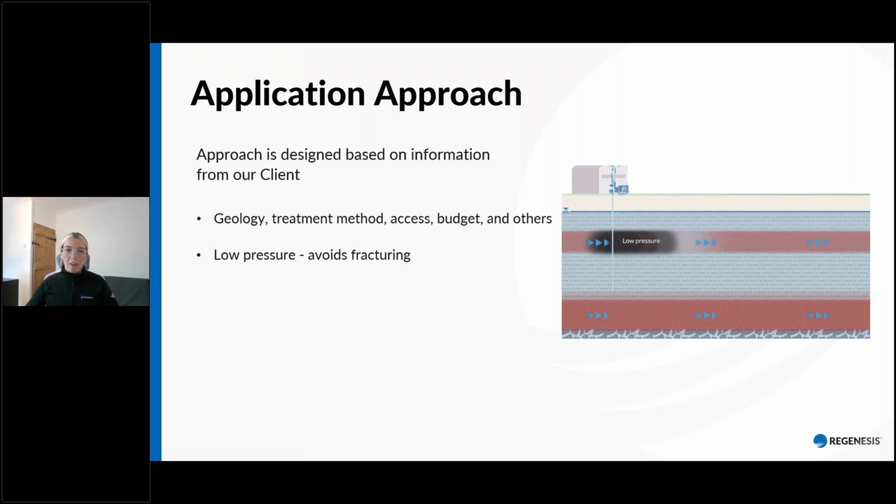So the video on the right demonstrates the application of a colloidal product in the near surface and powdered product at depth. And by injecting colloidal products under low pressure, we can achieve good and homogeneous distribution. Now, if we were to inject non-colloidal products under high pressure, you can see how we might observe uneven distribution and fracturing of the subsurface. So not only are you getting a technology which distributes well in the subsurface, it's also easy to inject.